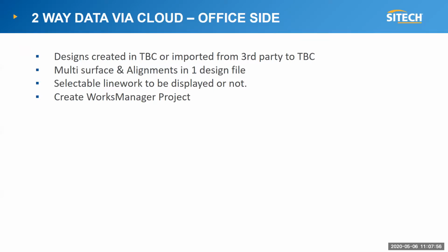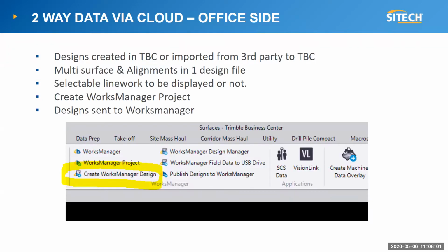So inside of Trimble Business Center, we have a special Works Manager option. So you can run it separately, or you can run it from within Business Center. Create your Works Manager project, so your boundary of your site calibration, that type of thing. And then here we say we want to create a Works Manager design.